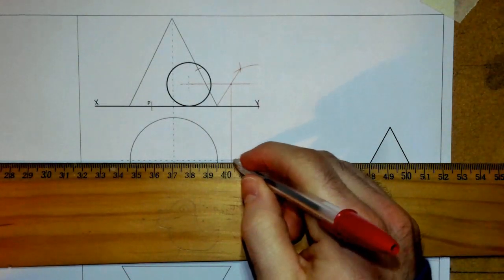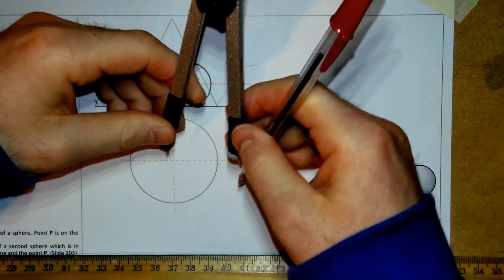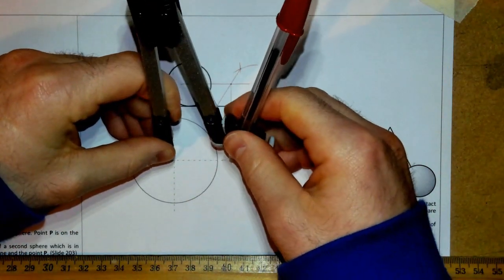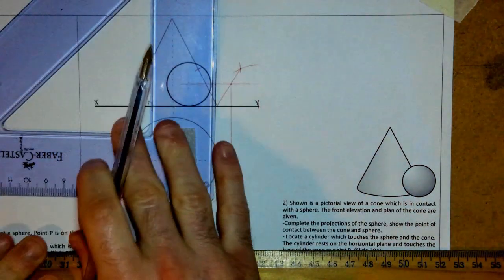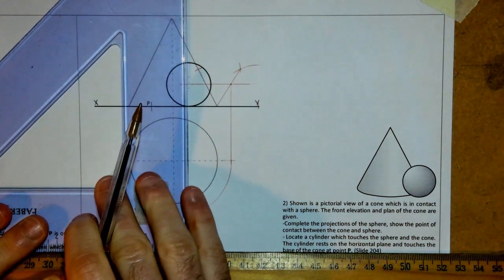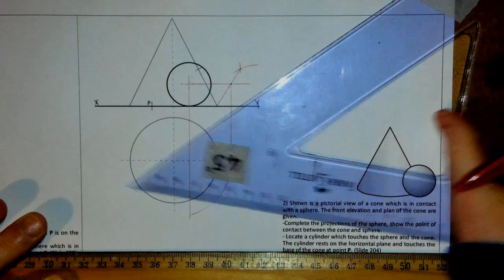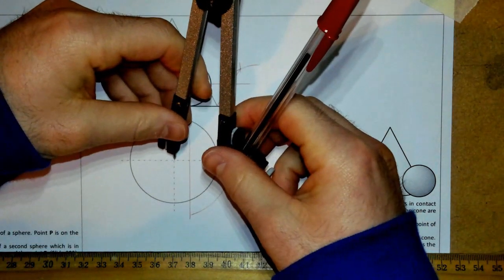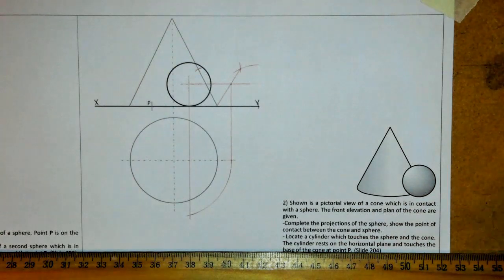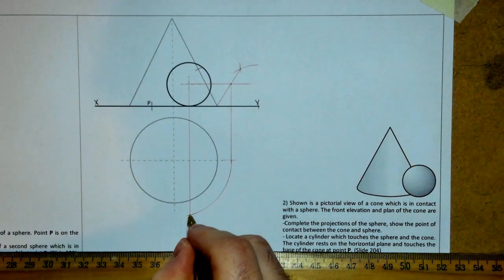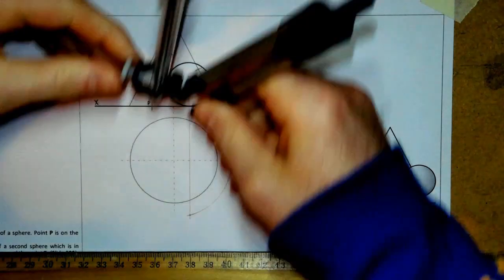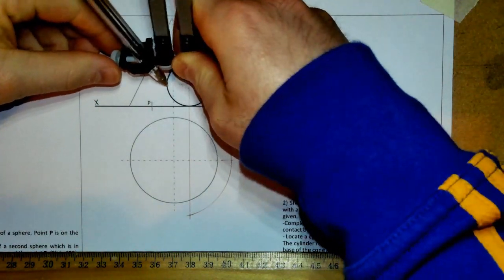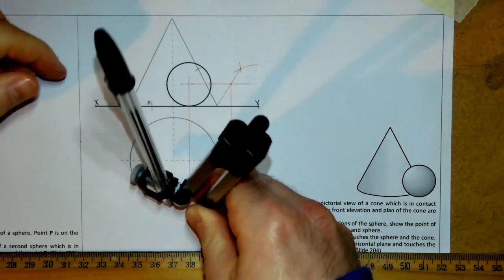Locate it here in position, project it around. It's going to be in there somewhere, and we know that in our elevation view, the position of the center of it is there. Project it down, bring that around just a touch further, and there we go. We have now found the position of the sphere in our plan view. Okay, draw that in. So take the radius from up here, the exact same, just draw it in down here in plan.